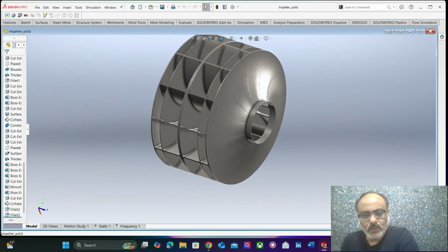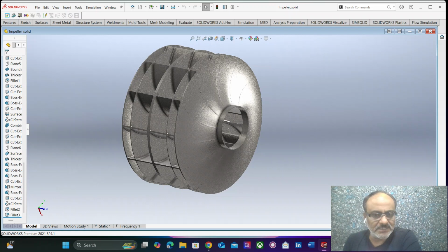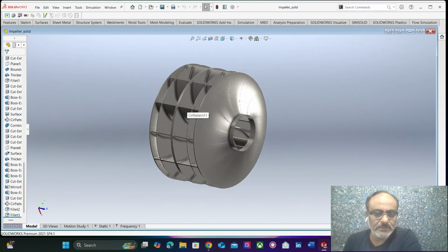So now when the air enters inside, along with the shaft rotation, that has a specific amount of kinetic energy. And now this kinetic energy is radially distributed, and that completely gets converted into pressure energy. And this pressure energy is what is expelled out of the gaps. So this is the actual process of an induced draft fan radial impeller.